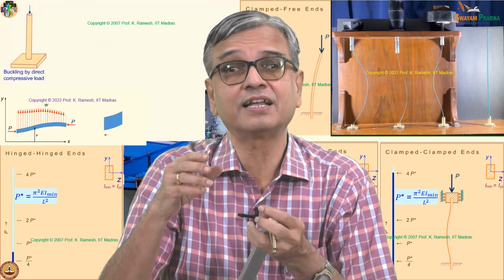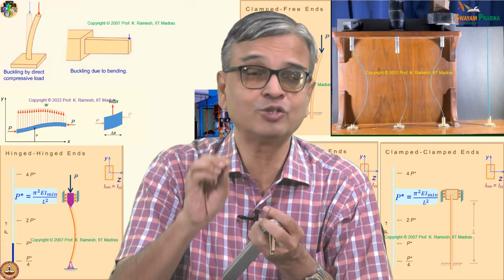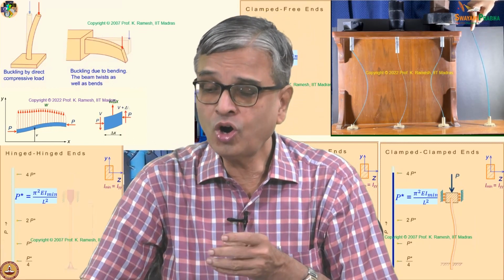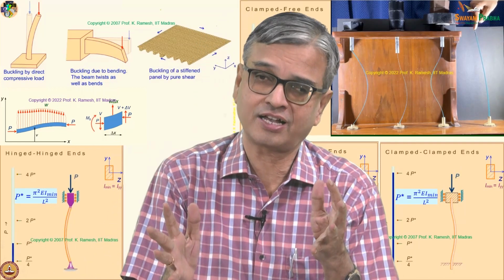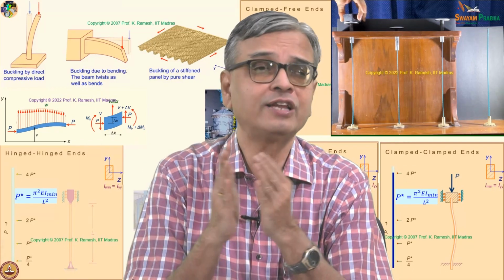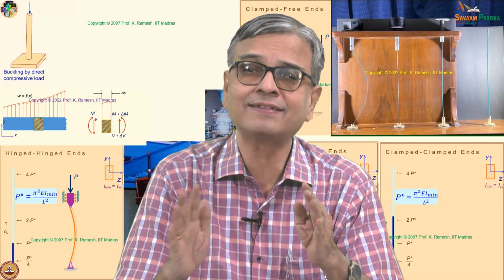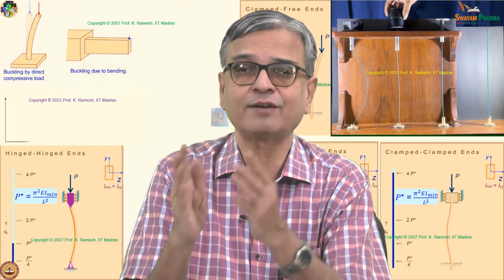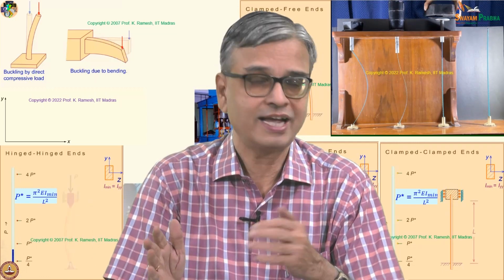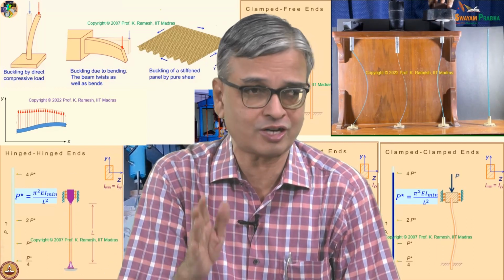That means if you want to idealize this as fixed end, you are also justified, even though you make a small error. So, in reality, you do not know how the constraints are. We always do the boundary solutions. That is, I will have an upper bound and a lower bound. I will do the analysis as pinned and then get one number. I will also repeat the analysis with fixed. I get another number. So, between these two I should operate. That is how engineers work.